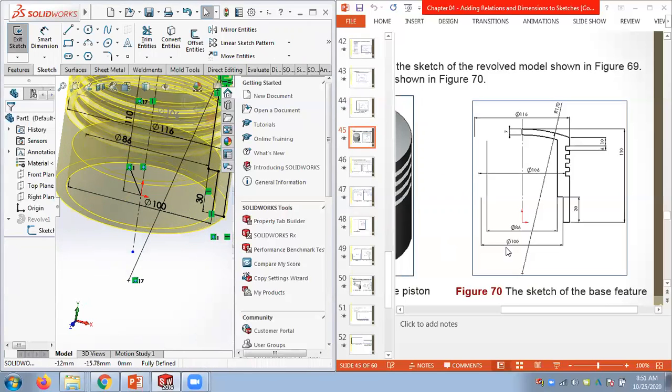I hope you understood why I put 186, 106, 116 without giving 50, without giving 43, without giving 53, without giving 58. Why did we do it this way? So when someone reads the drawing here, he can understand this is a circular shape and it has a diameter. That's why we gave the dimensions this way without giving half values. So this is a section. So we gave a sectional drawing. This is enough for the manufacturing.